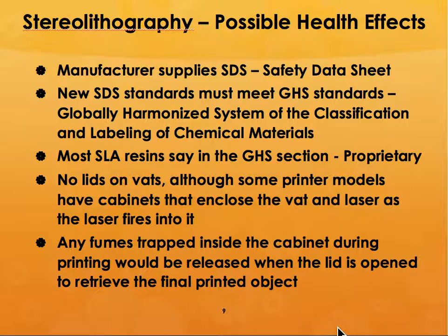Nowadays, the new SDS standards have to meet something called the Globally Harmonized System of classification and labeling of chemical materials. And the biggest problem I see, and this is my personal opinion, okay, is that most SLA resins say in the classification system that these resins are proprietary. So you really don't know what exactly is in the resin.